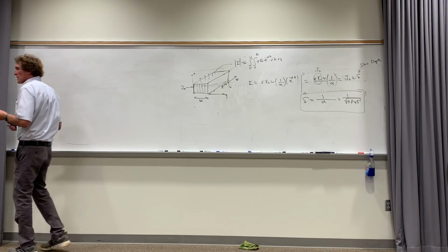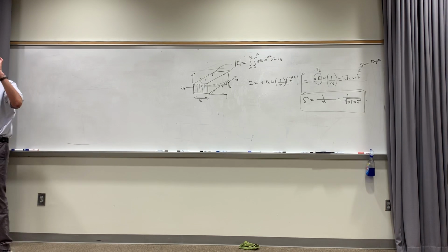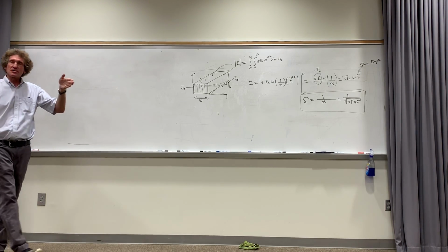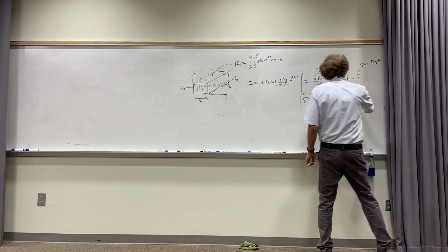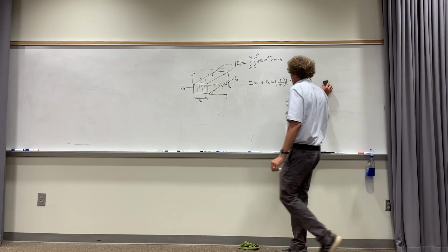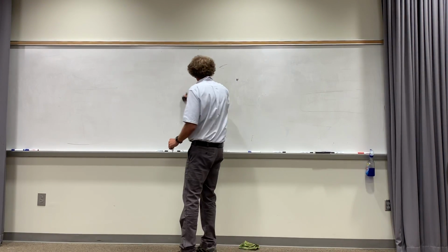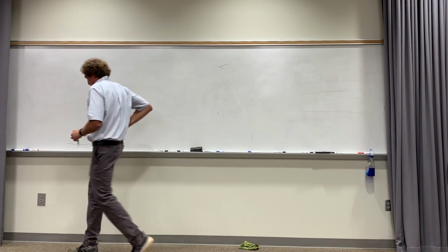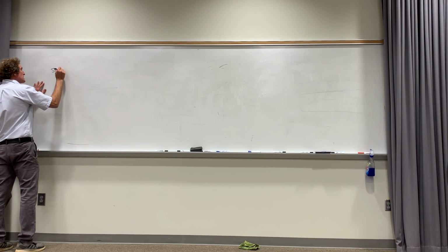Have you realized that a lot of times when you're at high frequencies, they don't use solid pieces of metal? They have hollow pieces of metal. Does anybody know this? Well, the reason is that all the current's on the surface. None can penetrate down to the core because of the skin depth effect. So they developed something called the high frequency resistance of wires rather than just low frequency. So let me go through an example of skin depth.